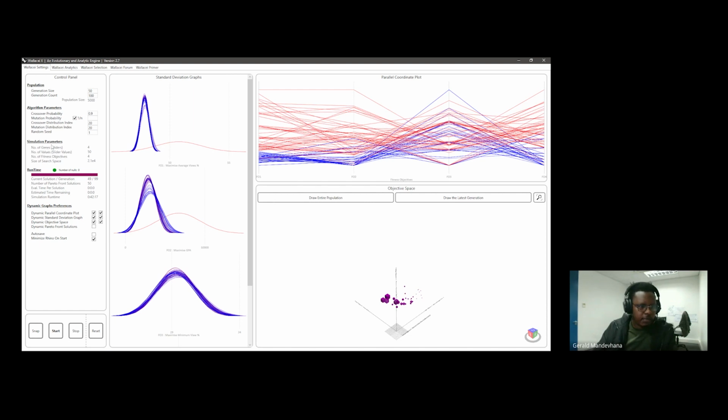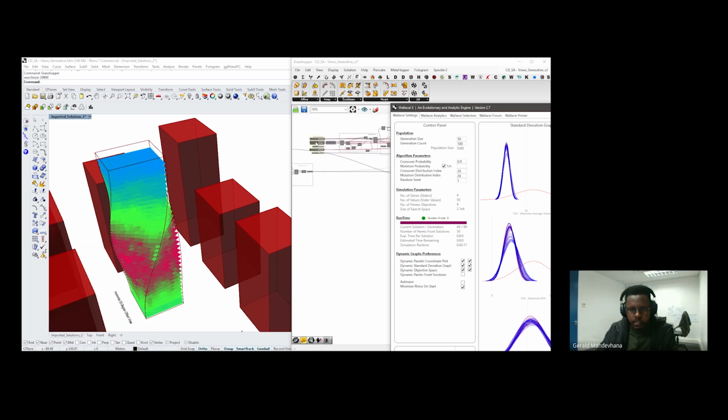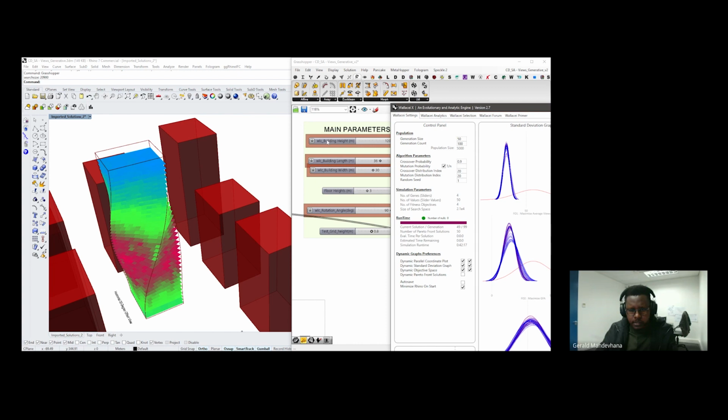Setting these parameters gives a certain depth to our design space, and determines how long this is going to run. The parameters you see here are extracted from your Grasshopper file. The number of genes is the sliders we're using: we have 4 sliders, which speaks to these 4 genes you have here.